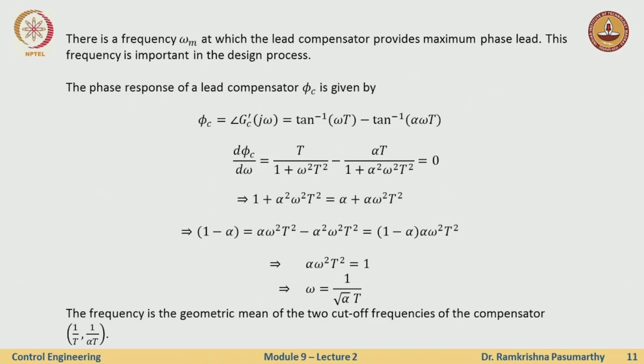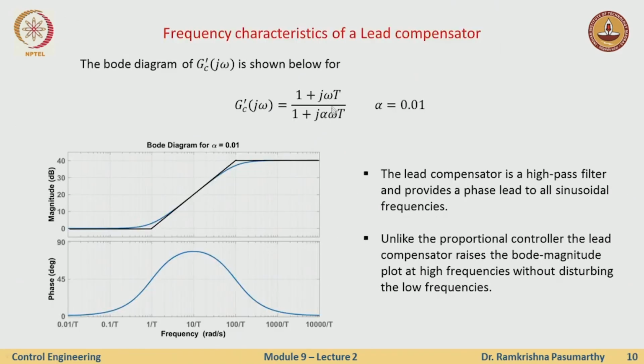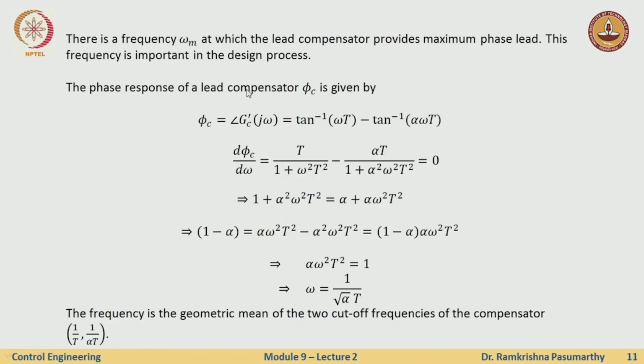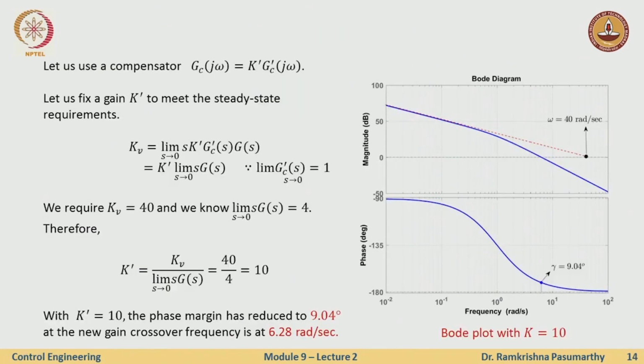Okay, why is that obvious? That is obvious because if you just substitute omega equal to 0 here, you always get 1. So this really does not contribute anything. That is also an indication that nothing really is happening with this compensator for the steady state error. It does not contribute anything, either positive or negative. So I am just left with these expressions.